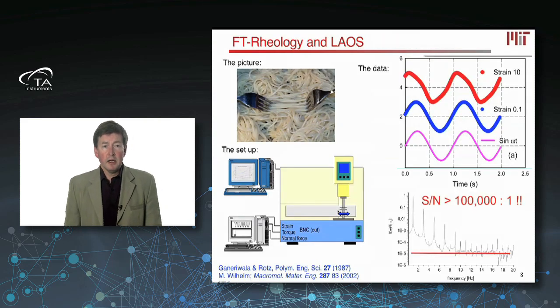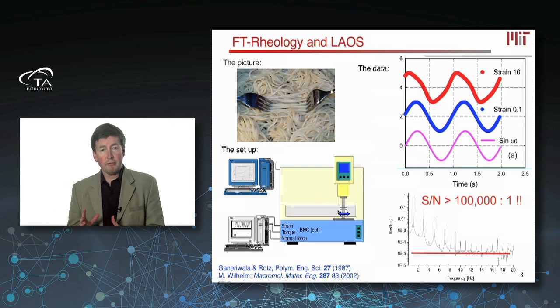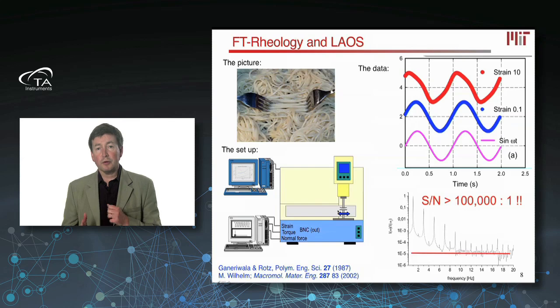Okay, so the way we typically do that in a rheometer these days is not by looking at shapes of ellipses, but by actually using Fourier analysis. So within the computer, a Fourier transform is taken of the signal, and then we look at the harmonic components of that. And so I've shown you here 3 plots. The magenta plot is the input signal. That's a perfect oscillating sine wave.